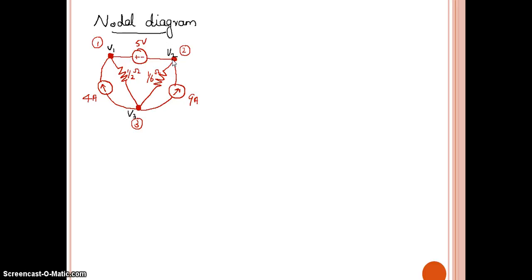Now look at this node. If I want to apply Kirchhoff's current law over here, see, a current source is coming here. This branch I can find the current. What about this branch? Here again the same. There is no current given, only the voltage source. And that voltage source is common to these 2 nodes. So here this node alone also I cannot apply Kirchhoff's current law.